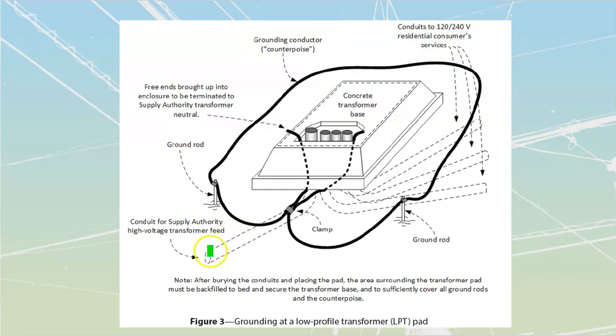What we do is we supply one conduit. That's going to be the high voltage conduit. That's that one right over there. That is going to be coming from wherever BC Hydro is going to spec it. We are then going to take another set of conduits. We're going to run one out to every single residence inside of there. They're going to get one. In some cases, they actually require you to have two, an heir and a spare, so to speak, in case one of them gets damaged, so they've still got an alternate pull path. Other times, and this is all going to be governed by Hydro, they will require that you run out sufficient for the number that are in there, and sometimes they want one or two just run out and then capped off underground, stubbed out, so that if somebody had to dig, and attach anything else, they would have one that they could attach into.